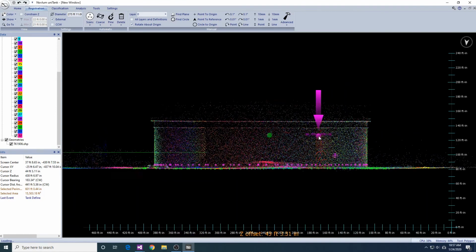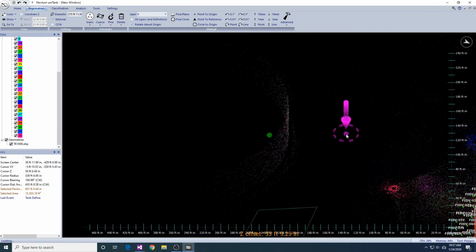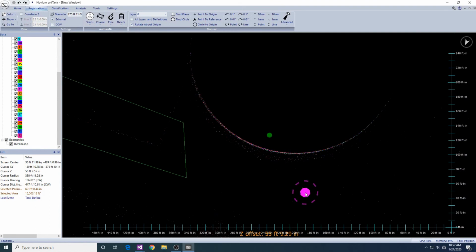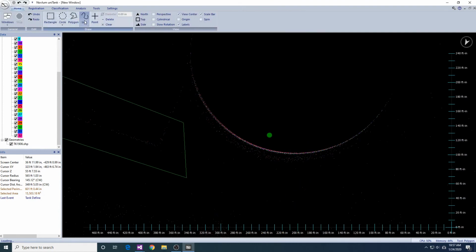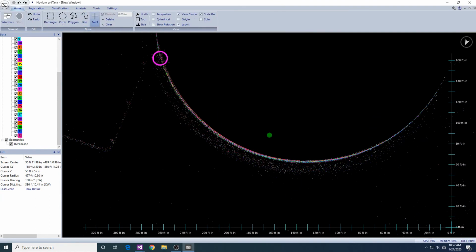We want to use surrounding tanks as much as possible. Due to the noise level in some of these surfaces and separation between scans, fiducials may not always get placed on them. Manually add horizontal fiducials on surrounding tanks if they are missing. Make them nice and big so that the fiducials overlap the tank in all layers.